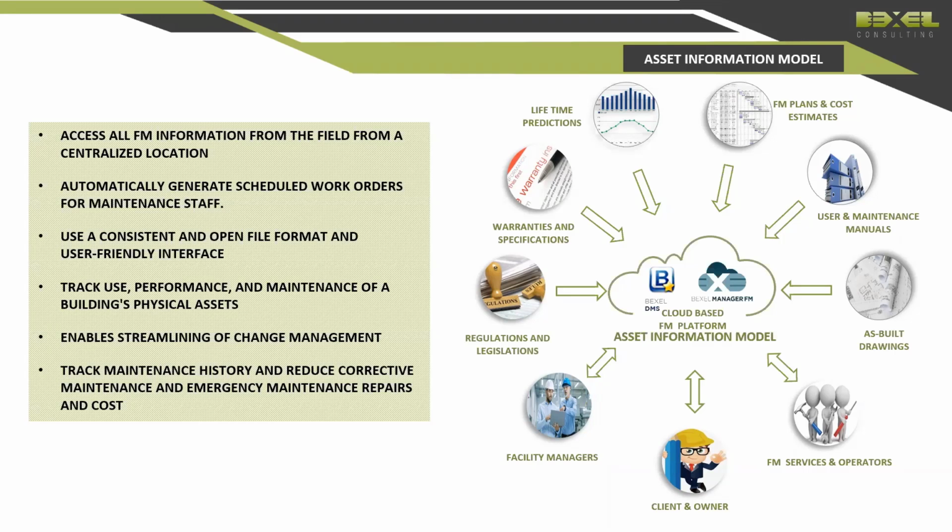So in order to use all information from the BIM model, usually the client requires COBie information or COBie sheets, COBie spreadsheets, which are Construction Operations Building information exchange, a standardized data format for the publication of BIM assets, which are usually formatted as Excel spreadsheets, or as a machine readable format. So it means that the other solutions which are not BIM based can use these kinds of documents and read all the information which someone populated, and they can access all the information from these Excel spreadsheets, and then they can use it for facility maintenance purposes.